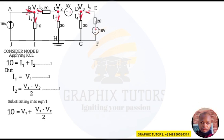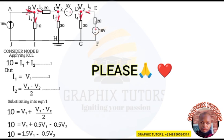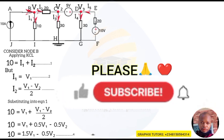And if I simplify this further, we have 10 will now be equal to V1 plus, now the coefficient of V1 here is 1, so 1 divided by the denominator will give me 0.5 V1, minus the coefficient of V2 here is also 1, so 1 divided by 2 will also give me 0.5 V2. So if I collect like terms, my 10 will now be equal to 1.5 V1, because 1 V1 plus 0.5 V1 will give you 1.5 V1, minus 0.5 V2. I will term that equation 4.